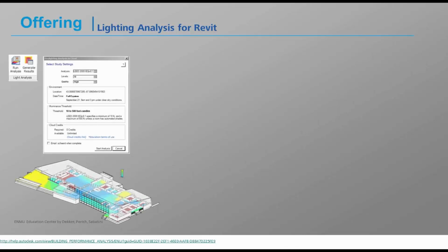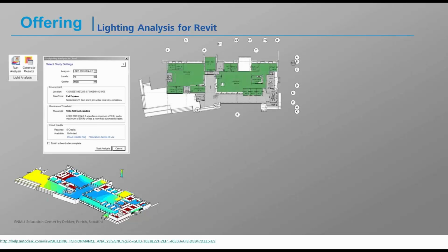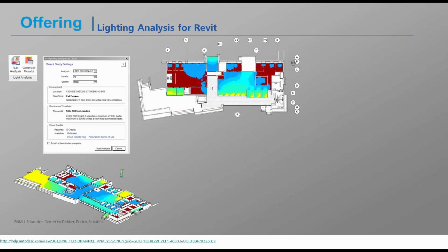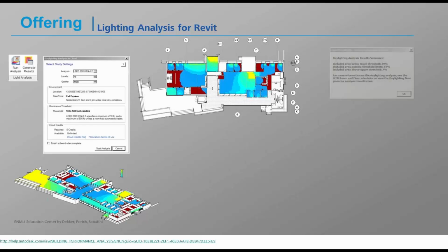Bring those results directly back into the Revit model, and show those results on the model itself. So these become a design artifact and something that is spatially generative. And use typical Revit tools, in this case the room objects, to define the regularly occupied spaces for LEED. And bringing those analysis results in, you're able to navigate through different results, in this case for 9 a.m. and 3 p.m., to see the overall results on the design.